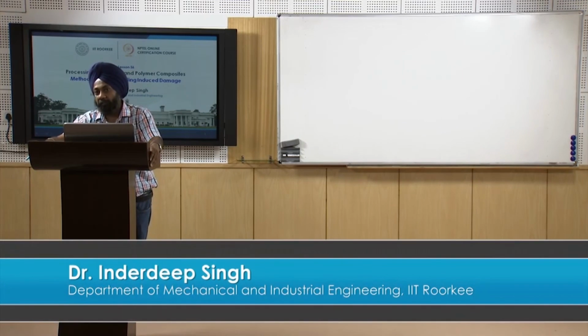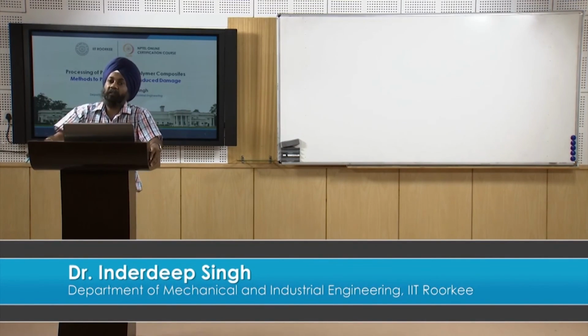We have seen that we can place a backup plate just below the composite laminate during the drilling operation, and the first method that we have seen is that we can use a woodpecker cycle in order to avoid the drilling induced damage. So all these three methods, the woodpecker cycle method, the backup plate method, and the helical feed method, are modifications of our conventional drilling methodology, and these modifications have specifically helped us to minimize drilling induced damage in case of polymer matrix composites.